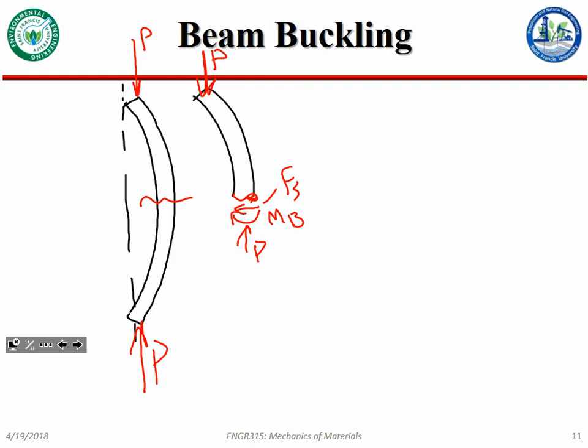So you have a shear force, we have a bending moment, and we have some axial load all being transmitted. This is all the same as when we talked about eccentric loadings, like if you had the open carabiner that was being pulled apart, or a C-clamp that's being tightened down. This is the same sort of internal loading that we saw there too, right?